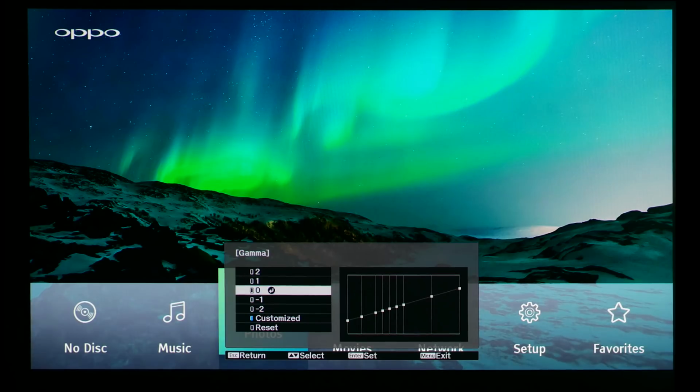Usually what some parties like to do is to design a custom curve to make the image more palatable, because projectors, because of their generally lower light output, generally don't do HDR justice. HDR content can go up to 1000 nits or 4000 nits during the mastering process, but projectors, nominally their lumens output or light output is at 48 nits, and so when you're trying to cram all this extra dynamic range into such a limited light output, it is always going to be a struggle, and a customized gamma curve can allow you to mitigate some of that.